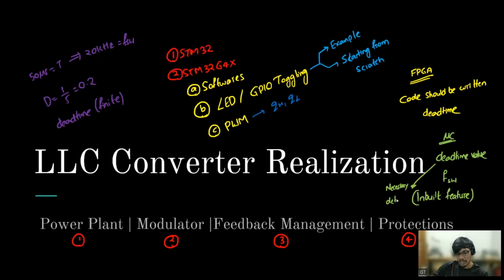There are some functions which understand this, just like delay. In an FPGA LED delay, I wrote the delay time and everything in the code, whereas here we have used a function, HAL_Delay. Similarly, there are small modules or functions which can be used to do specific tasks, so not necessarily do we have to write the code in detail.